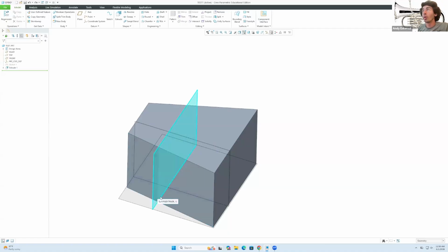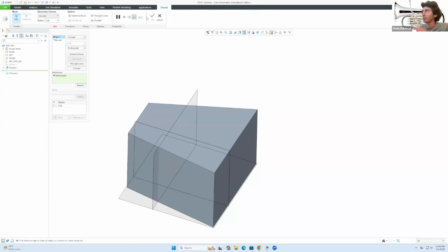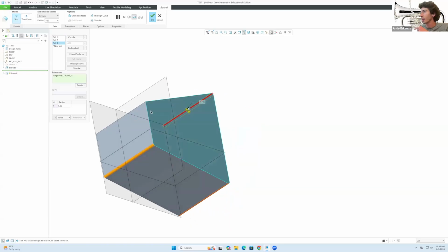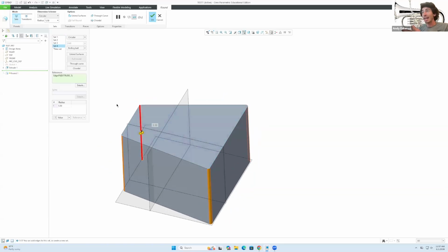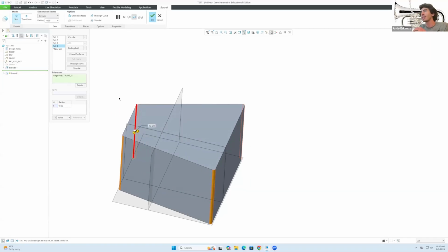What else can we do? Well, a couple of things that we could say is the fillet that I was mentioning and the chamfers. These are features that appear right here. For instance, I can click here where it says round, and I can click on that edge, that edge, that edge, and that edge. And now we have them all appearing here, and I can specify a radius of 10 as an example, right? But 10, if I'm not mistaken, is only going to be on number 4.